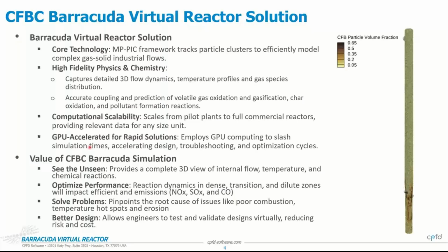And essentially, the idea is that you can do all of this on a digital twin. So maybe you carry out some experiments on your lab scale. You build a small CFD model, you validate it, looks good, and now you're trying to scale it up. But you're doing all of this scale up on your digital twin rather than on your real system. So you solve these problems inside the software, you gain the confidence before you start actually building up some equipment here.